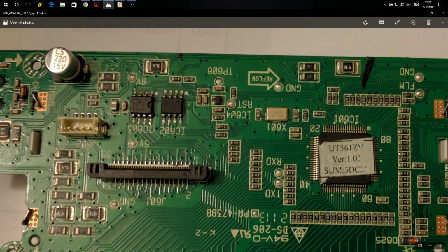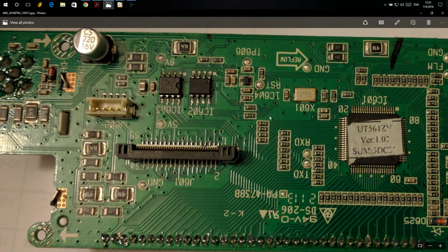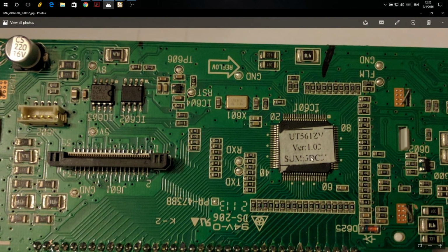When I attach my Saleae Logic to the bus, it won't boot. In fact, if I try to put resistors between my Saleae Logic and this bus, it still goes weird. That's when I get the EEPROM corruption. So I think there are countermeasures in here to try to prevent you from sniffing the bus, but I've been successful at doing it because those sorts of countermeasures you can get around. They're just, as a famous YouTuber says, trap for young players. So if you're going to probe around on this, you have to be careful that you don't trip some apparent countermeasures that they have in here.